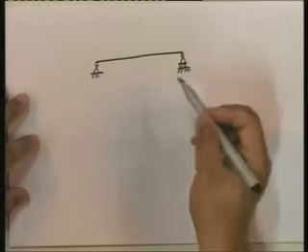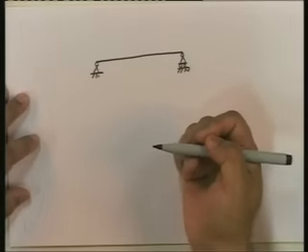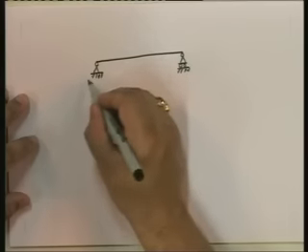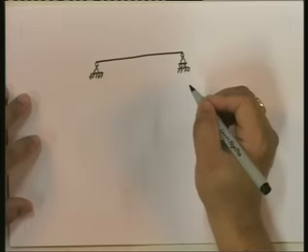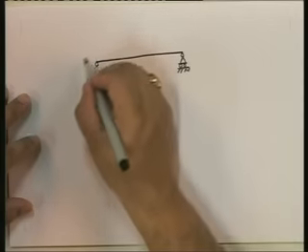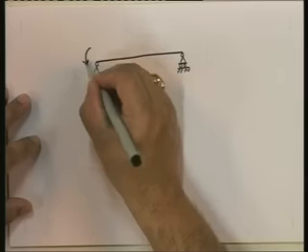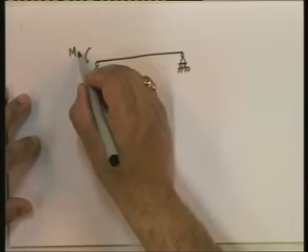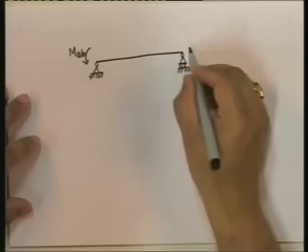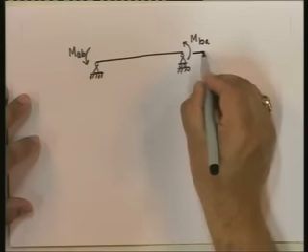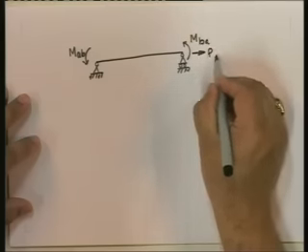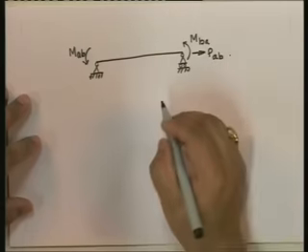Okay, because you can always invert the flexibility matrix and get the stiffness matrix for a member. Okay, I've already shown that many times. So let's go back to this. And here, what we have is MAB, MBA, and PAB.